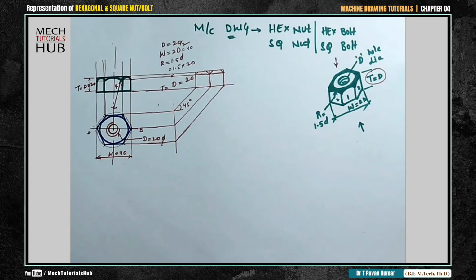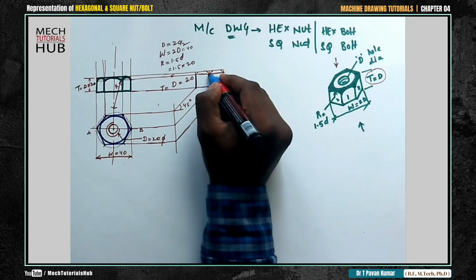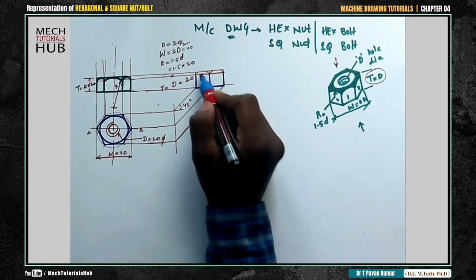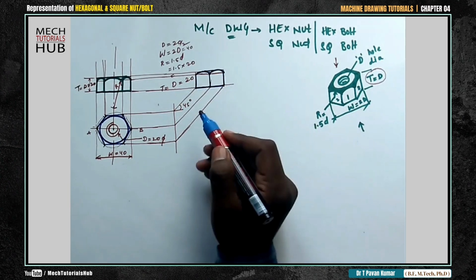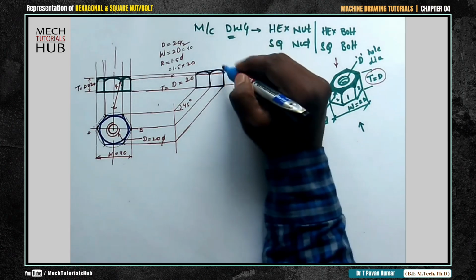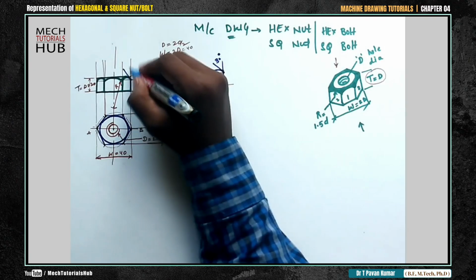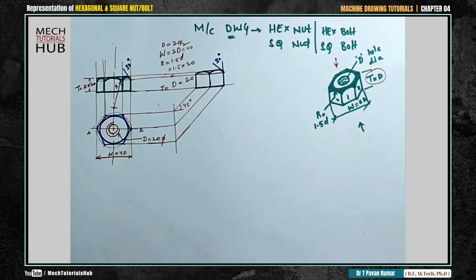With the HB pencil, darken the required lines. 1, 2, 3, 4, 5, 6, 7. Okay. These are the required side views. You need to maintain an angle of 30 degrees here, and here also 30 degrees. That is more important. In a few cases they may go with 45 degrees inclination also. In this case 45 degrees inclination also, but no problem if you go with 30 degrees.